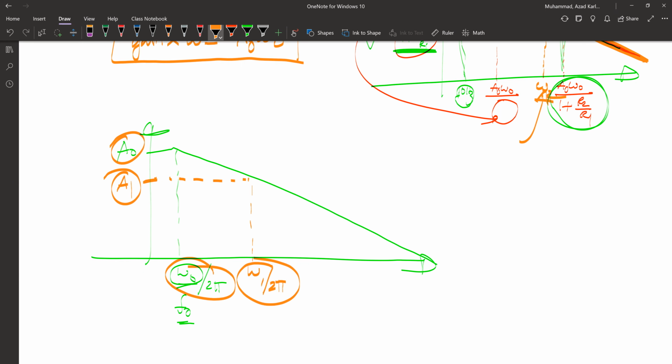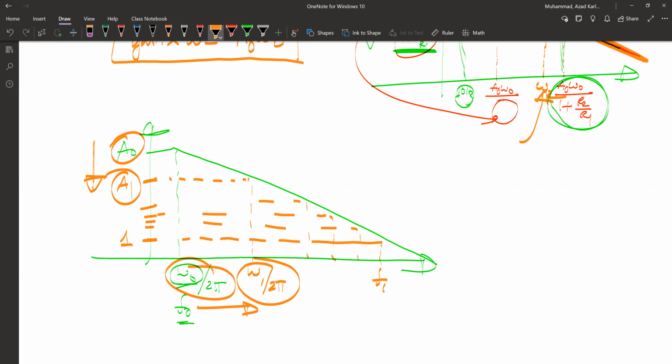Does that make sense? And see that because I'm sacrificing the gain, I'm getting higher bandwidth. And if you pick any gain, you'll get the corresponding bandwidth. Now, if I pick a gain of 1, what happens? I get a specific frequency. Let's call it unity gain frequency.